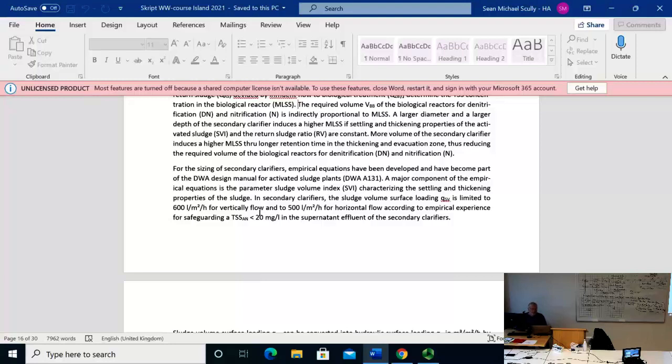The depth of the tanks normally is not much more than 4 meters, because going deep in the ground is very costly. And somewhere you're going to hit, because normally you construct your wastewater treatment plant close to a receiving water body, so if you go too deep, you're going to hit groundwater. And to make constructions in groundwater, you need to pump away the groundwater, and all this kind of stuff is very costly. So you try not to go too deep. So 5 to 6 meters is mostly the limit; we try not to go deeper than that.